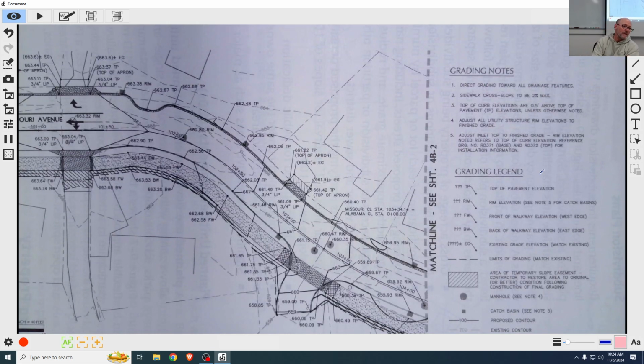Okay. So a typical sidewalk, what, 5 feet? I don't know. Let's say it's an 8 foot sidewalk for that matter, just to be easier. And 2% of that would be 0.16 feet. Yeah. So 16 hundredths of a foot. That's 2 inches. So the sidewalk can't tilt more than 2 inches one way or another for an 8 foot sidewalk.